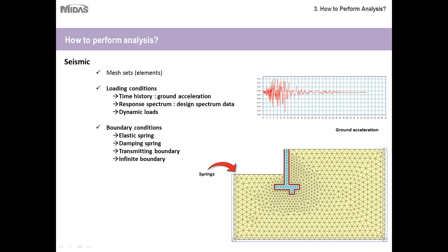So once you have got the basic ingredients in, which is the mesh and the internal condition, it's just a matter of playing with the external conditions, like how loading and boundary conditions are to be applied prior to analysis in order to get the desired results.